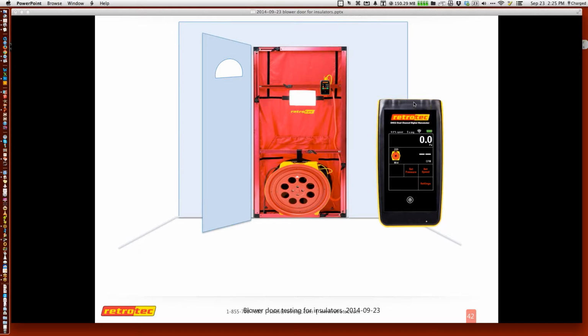Now, when I add the manometer, this is the DM32. Channel A is on top, and channel B is on the bottom. Channel A is going to read the pressures of the fan, and channel B is going to give me the results that are converted to CFM or anything else I want to do for that.